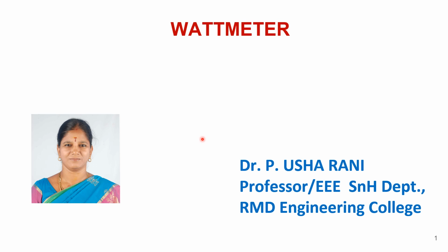I am going to brief about the topic of wattmeter. A wattmeter is an electrical instrument which is used for measuring the active power consumption by combining the measurements of voltage and current. Generally, the active power formula is voltage into current into power factor, VI cos phi. We are going to see two types of wattmeters.